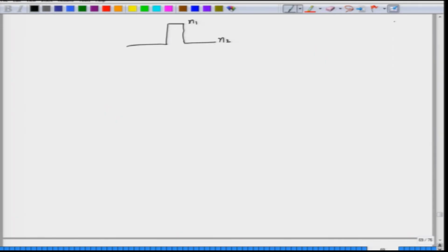This is very similar to the optical waveguide that we considered, the slab waveguide. Here in the slab waveguide we took n1 and we took n2 to be less than n1. This is precisely the same scenario in terms of the refractive index profile. Unfortunately, the geometry that we have chosen in this fiber is not the same as the planar geometry that we had for the slab waveguide.